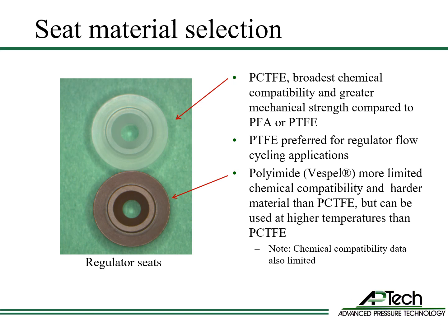Polyimide has limited chemical compatibility. It is not compatible with strong acids and bases, but has much higher operating temperatures than PCTFE, PFA, or PTFE. A polyimide seat in some chemicals, such as ammonia, will dissolve.